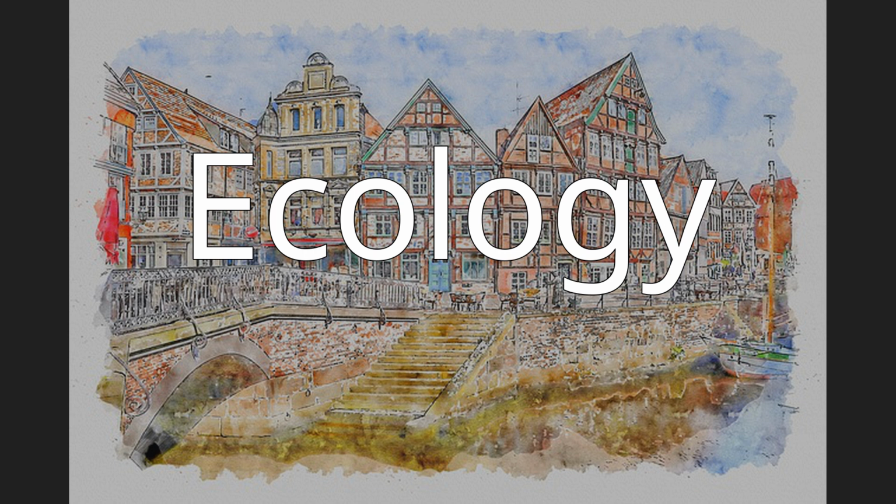Ecology. Because a weir impounds water behind it and alters the flow regime of the river, it can have an effect on the local ecology. Typically, the reduced river velocity upstream can lead to increased siltation, deposition of fine particles of silt and clay on the river bottom, that reduces the water oxygen content and smothers invertebrate habitat and fish. The oxygen content typically returns to normal once water has passed over the weir crest, although it can be hyperoxygenated, and increased river velocity can scour the riverbed, causing erosion and habitat loss.